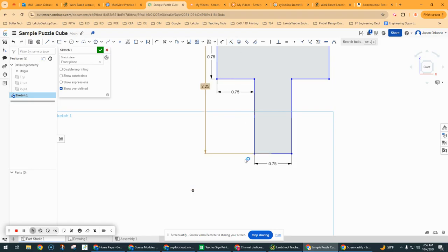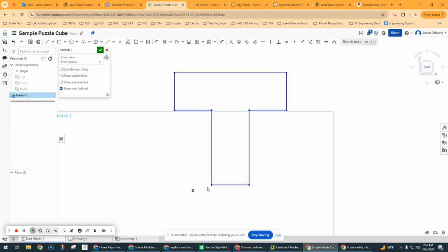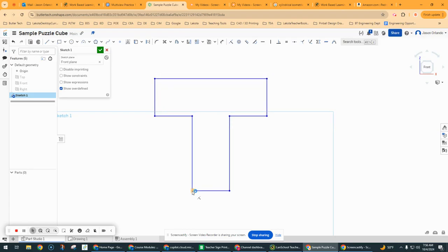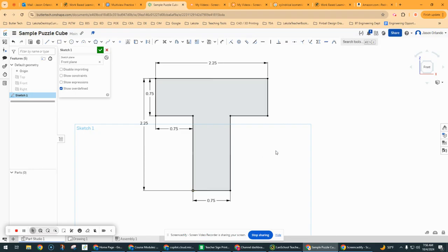Or we can simply drag, okay, if that tool's off, you can actually drag 1 point over onto the origin. I'm holding down my mouse button, and then when the origin lights up orange and the little coincident constraint shows, I can let go, and it does the exact same thing. Notice the sketch went from blue to black.